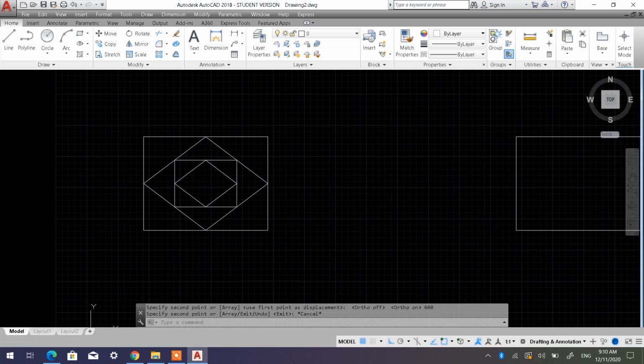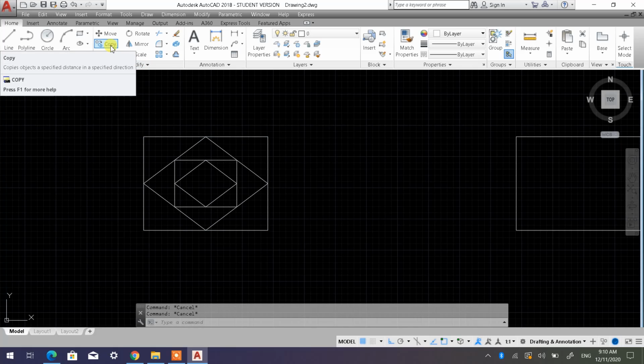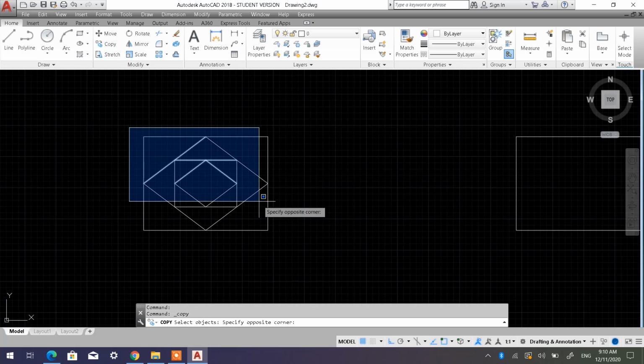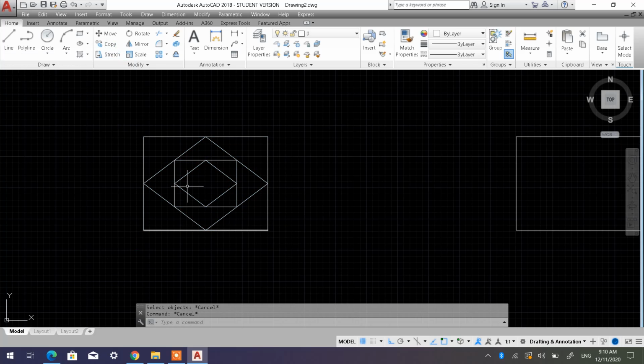Alright. Okay, once again, if I copy, press copy first, and if you want to select just one, you can. 1. We choose C, 2, 3, 4. So it is better you do the box selection like before, it is easier. Okay. If you select this and copy, I press the escape button to exit from the command. If you select copy and start from here, it will select everything. Okay, since I just want to select this one, 1, 2, 3, 4, you can click copy and select one by one, or like the box I mentioned earlier, from the bottom just select whatever touches.